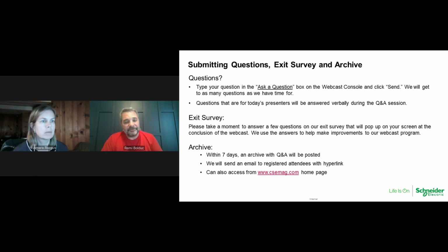Well, thank you for the question, first of all. Typically, most of the time, it's to eliminate utility power factor penalty. But if doing it at low voltage, that's where you have optimum compensation, because you reduce your losses throughout your system, and also improve how much power you can supply by that distribution, because you reduce apparent power from the low voltage distribution. And I've seen in the example there, that I showed earlier, we had a reduction of 20 kVA.